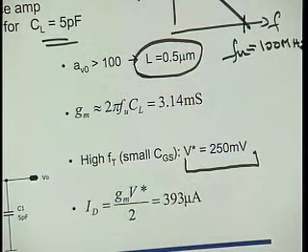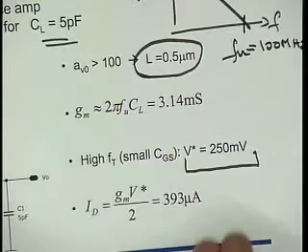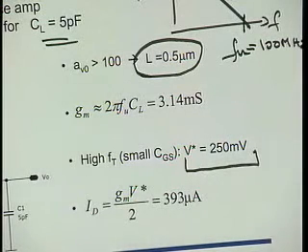But we've sort of seen that a couple of 100 millivolts is reasonable, so I picked 250 here. Then later we say, well, VDS min really should be very small, and consequently I use a lower value and so on. That depends on design experience, design requirements, and so on. I picked the value here.